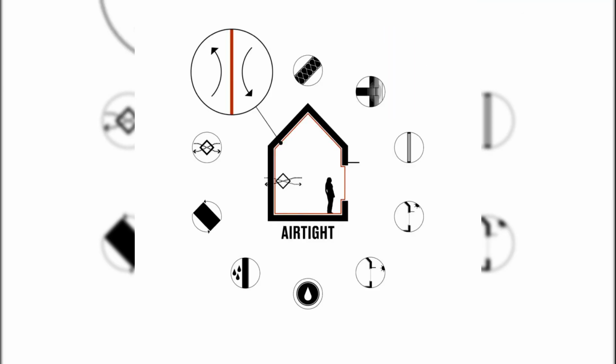Let's talk about airtight construction. The airtight layer in a passive house acts like a windbreaker, preventing uncontrolled air infiltration. How airtightness is achieved: sheet membranes, fluid-applied membranes, airtight tapes, and sealants. All components must transition seamlessly to maintain an unbroken barrier. Airtightness in a home is confirmed with a blower door test, a critical quality measure.